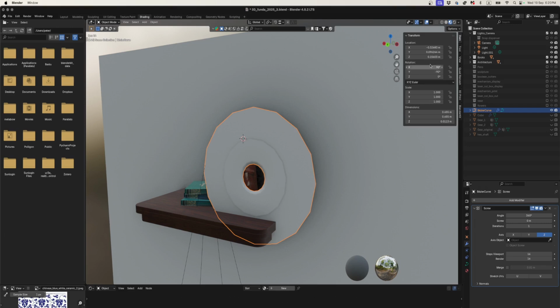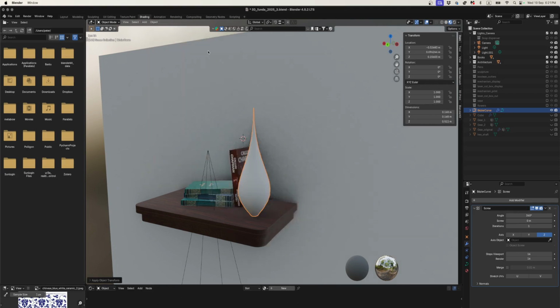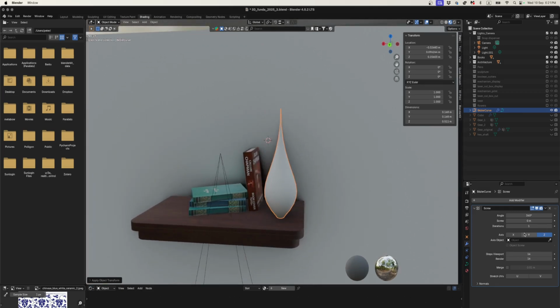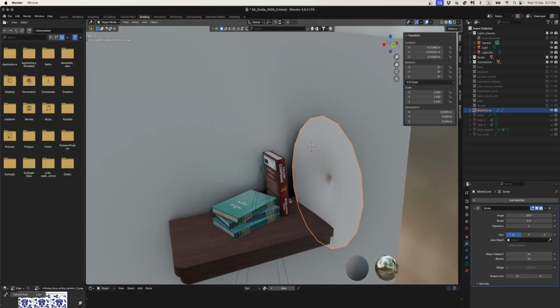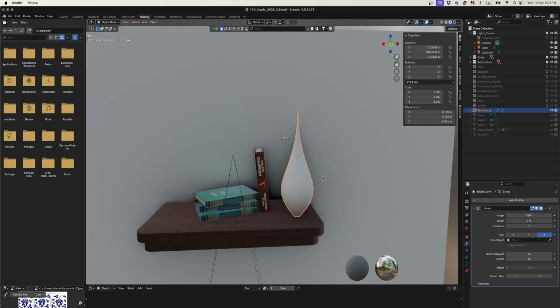The other thing is that we've rotated our curve. So let's apply our rotation. Control A to apply rotation, or Object, Apply, Rotation. And okay, so we're already facing the right way because our modifier says rotate on the Z axis. If I change it, it'll rotate on different axes. Oh no, there you've got almost a hat or a symbol if you're making a drum kit. But okay, let's keep it on the Z axis.